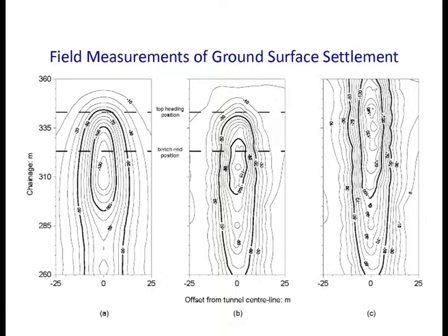This is the nice thing about a 3D analysis. It can actually give you some insight that you never are aware of. And that is because the interaction between the hardening of the shotcrete, the digging and the unsupported length, the supported length and all that is very complicated. So basically, it also tells you that you cannot dig too fast because then your shotcrete is not hardening enough when you go forward. You know. So basically, this is one of the things.